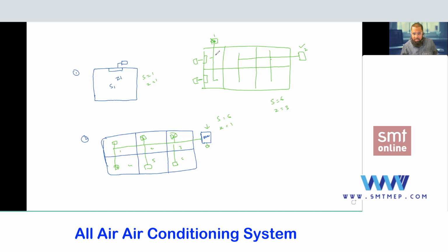And in this case, for space 1 and 2, if the timing and temperature are the same, you can connect with this one AHU. If the timing and temperature are different for space 1 and 2, then you cannot connect. It would be unnecessary loss of energy. In this case, this section will consider a partition in calculation, because the timing and temperature are different. I think we already discussed this at the time of load calculation, when the partition is applicable.